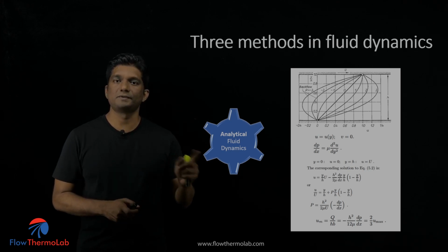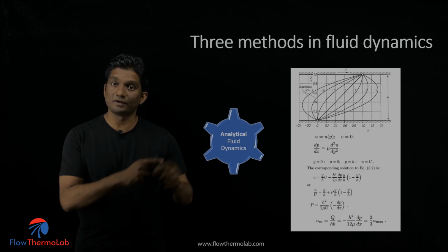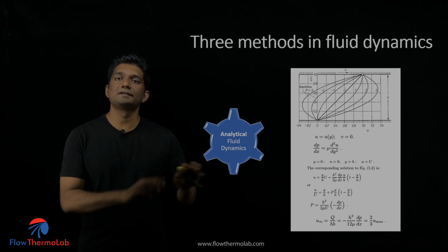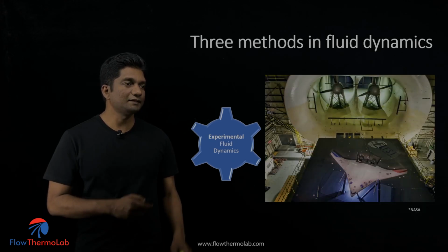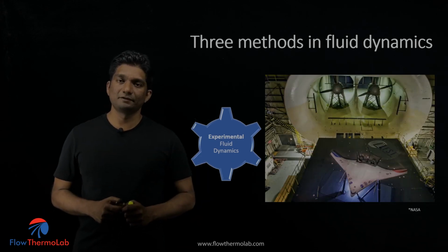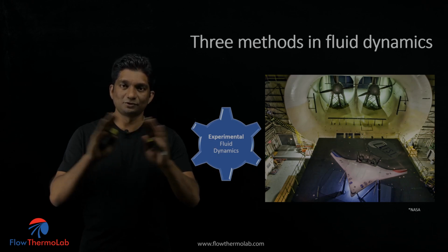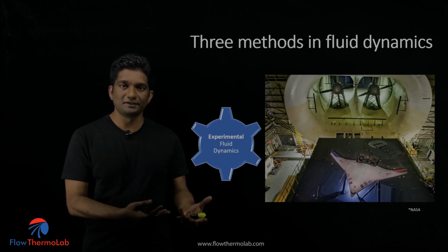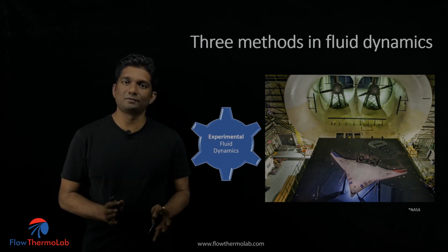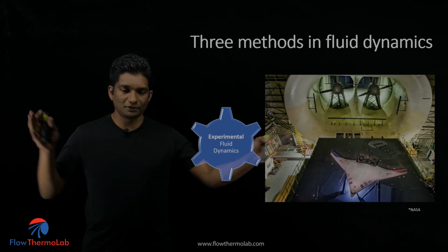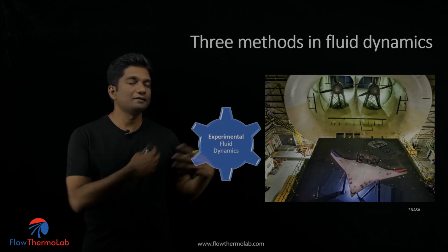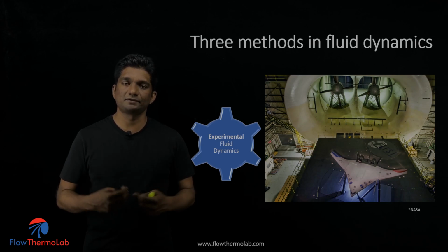Even in the industry, people are working on analytical solutions and 1D solutions, right, from analytical solutions. So here it's all about mathematics and a little bit of programming. And the next method is experimental fluid dynamics. This is known as the ultimate truth, because you work on a real condition or maybe scaled down models, where you make the model into a smaller dimension using dimensional analysis, and then you work on this and try to understand the physics.